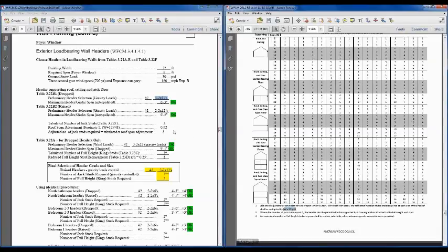So always look at the footnotes, figure out what those adjustments are, because we've got 9-foot wall heights, I'm sorry, because we've got a 32-foot roof span system. To make it easier to tabulate, we will use that adjustment. But it doesn't bring us down below requiring 3 jack studs in this system.